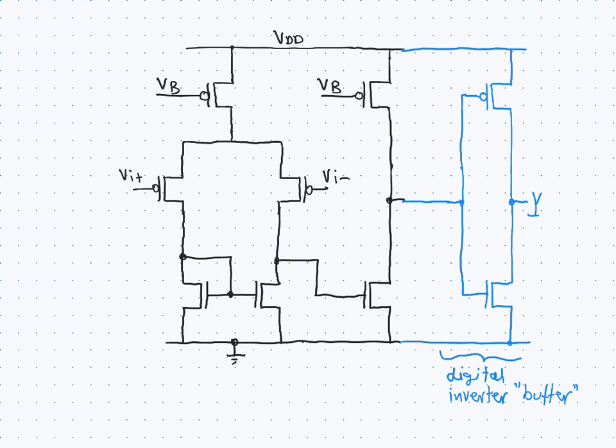What we have assumed here with putting in the digital inverter is that it is running on the same supply as the analog circuit, which is not necessarily the case, but it could be. Now, as for the normal op-amp or any other amplifying circuit, we can apply a PMOS differential pair as done here, or we could take a mirror image of the circuit and have an NMOS differential pair just as we did with the op-amp.